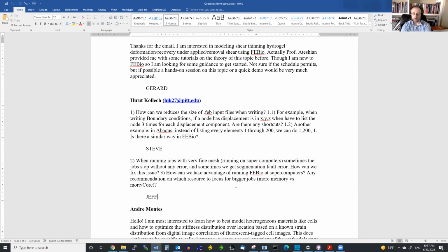I'm pretty sure it's going to seg fault, because that happens in a third-party library that didn't provide a mechanism to gracefully handle that kind of exception. So if you run out of memory during the allocation of the stiffness matrix, or actually the inverse of the stiffness matrix, the factorization, then it's probably going to crash.